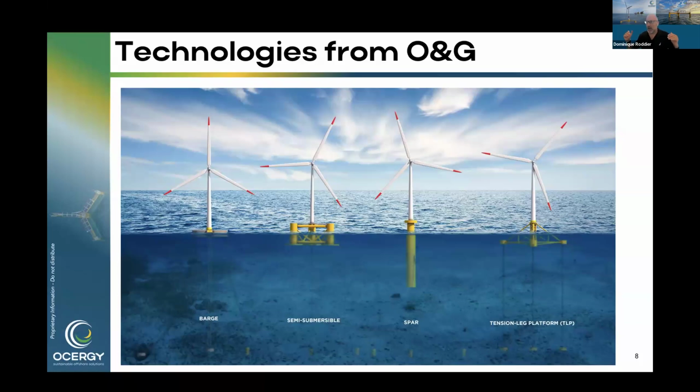In floating wind, you have absolutely no requirement on the heave motion, because your wind is very different at 10 meters than it is at 300 meters. So you have already taken this shift, and the turbines are meant for that. What you don't want is pitch and roll, but mostly pitch. So it's the rotation of the platform. The semi-submersible is wider, so you get more stability. It's kind of like a catamaran versus a sailboat. Your catamaran is much better. So it's a cheaper floater that has the right motion characteristics for floating wind. This is why you see that most of the new designs are semi-sub.